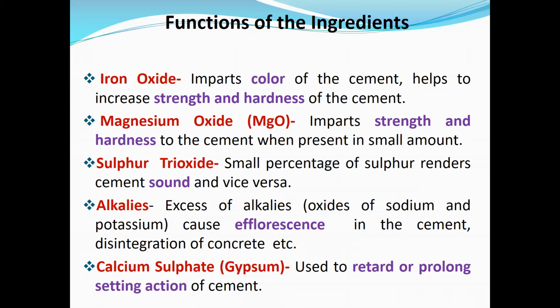That white powder is called efflorescence. If it happens due to the presence of alkalis and you don't treat it, it will cause disintegration of concrete.